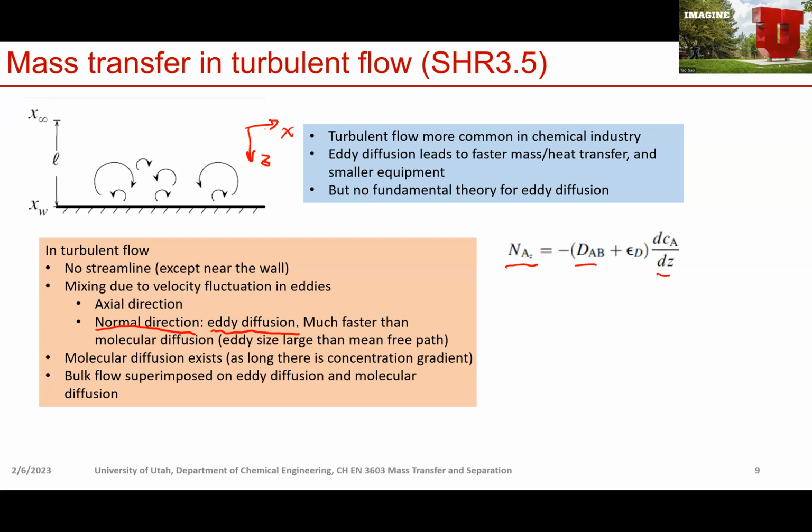So that's why eddy diffusion is somewhat similar to molecular diffusion, and why we can apply a similar functional form to compute it, so long as we add an additional parameter called the eddy diffusivity into this equation, just to modify Fick's law.